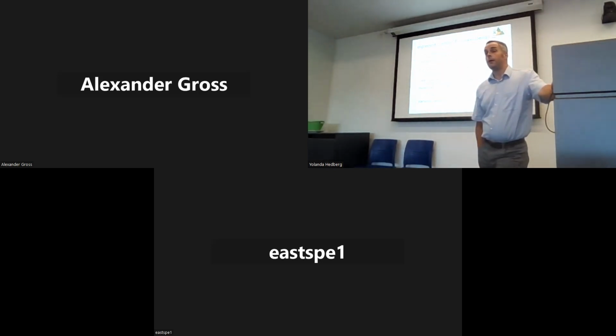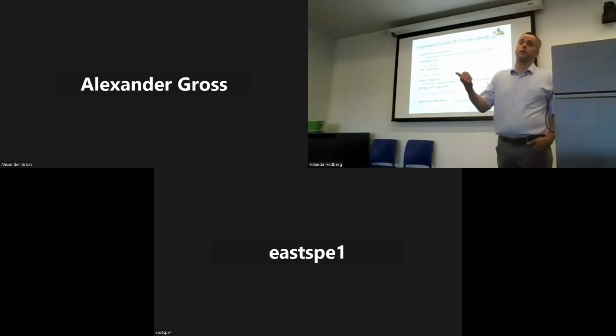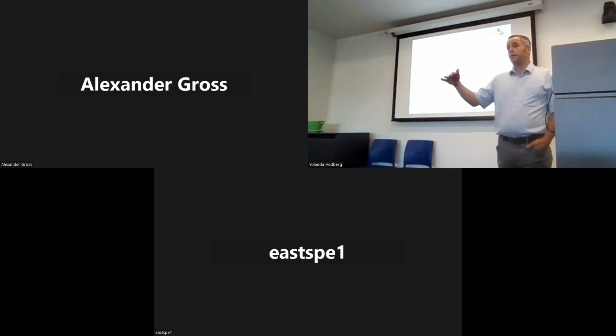There used to be concern that excess cathodic protection was possibly doing two things. One, blowing off the coating, which is true. We can create reactions on the surface that affect the adhesion of the coating, and the coating will fall. You can blister the coating.